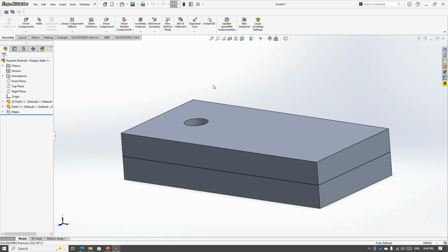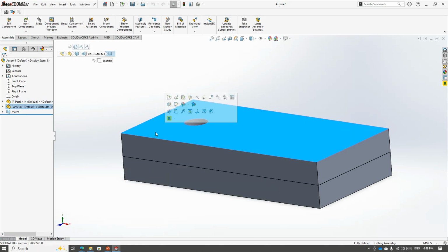You will not know which part of the design you changed, and it will be in reference to what other functions and features of the other parts. So to avoid that, at the start of your career, where you are not very aware and not very expert at SolidWorks, you need to just create the separate parts. Once you have all those separate parts ready, you will just bring them into the assembly, apply the mates and prepare your assembly.